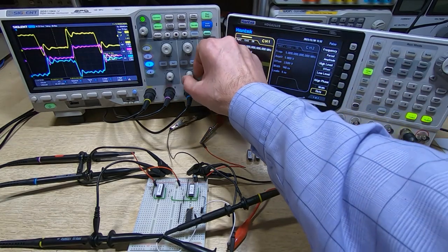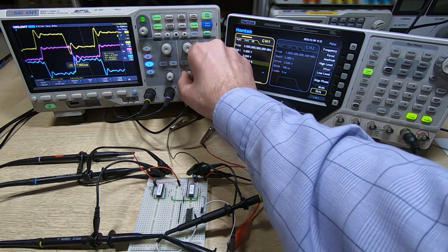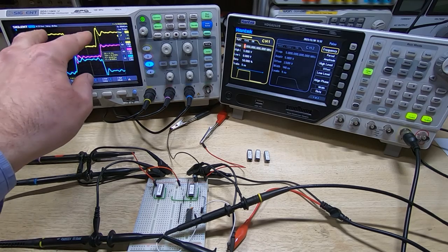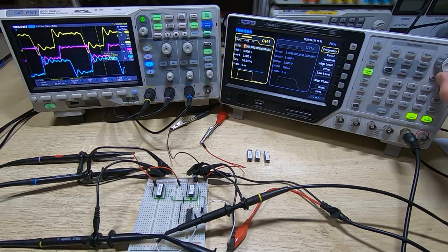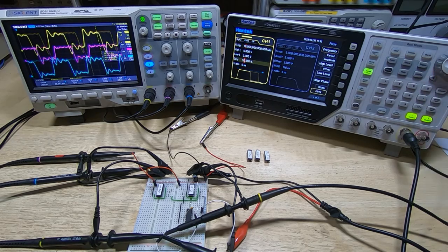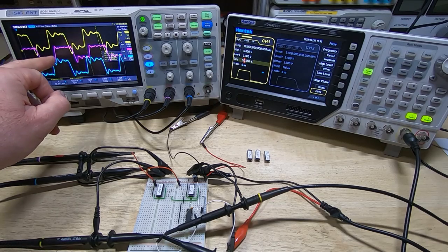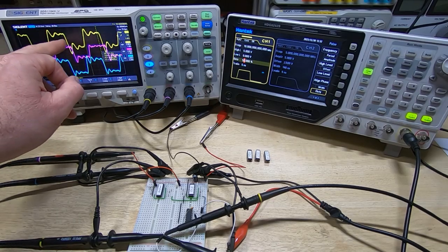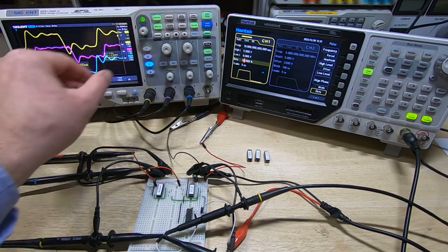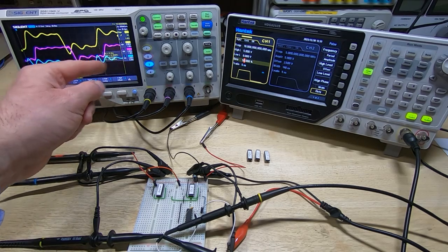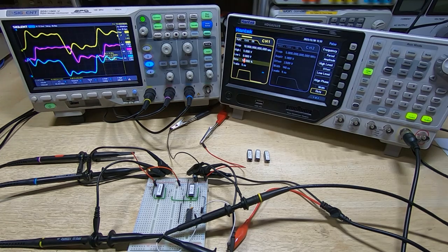And just for a bit of fun, we'll increase the clock still further and see how high we can go and still have the falling edge of the purple trace within the clock period. So we'll get up to 10 megahertz. So up at 10 megahertz now, you can see that the edge of the purple trace is still well within the clock cycle, and the blue is obviously, we're now actually one phase out completely with the blue cycle. It's nowhere near fast enough to meet the requirement. We'll go up to 20 megahertz.